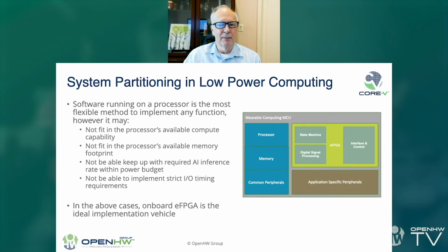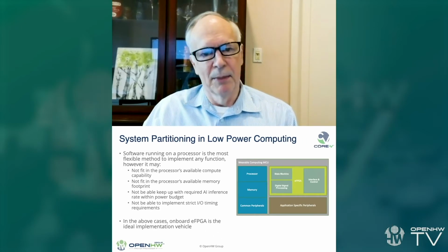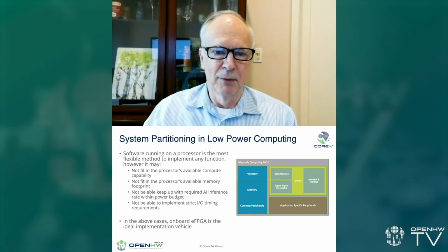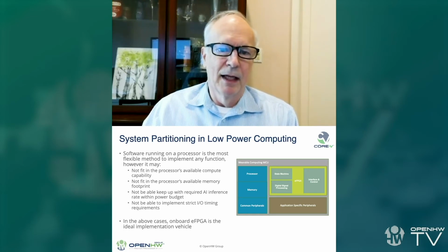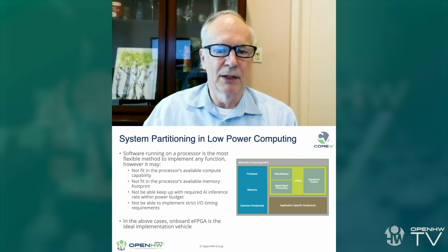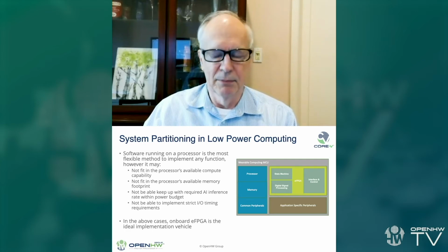However, it may not fit in the processor's available compute capability, especially in a resource-limited environment like IoT. It might not fit in the processor's available memory footprint, might not be able to keep up with the required AI inferencing rate within the power budget. So there are two sides to performance. One side is how much performance can you get at a given power budget, and the other side is just how much performance can you get, period. And it may not be able to implement strict I/O timing requirements. So this is the place where onboard eFPGA is an ideal implementation vehicle.